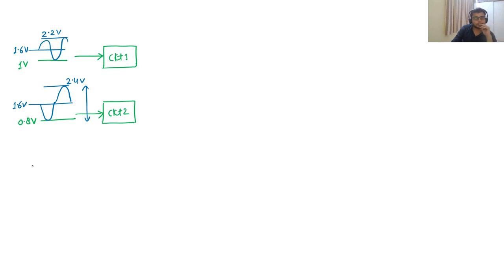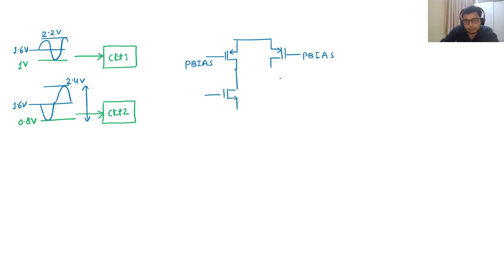Okay, one more thing, now we'll see if there is any effect on the higher value of outputs. In both the circuits we are using a PMOS current bias, so this is P bias, and the same common mode is used for this. So what is the higher value that you will see? One is this circuit and this bias. Now I should see this VCM max value. So what can be the VCM max?